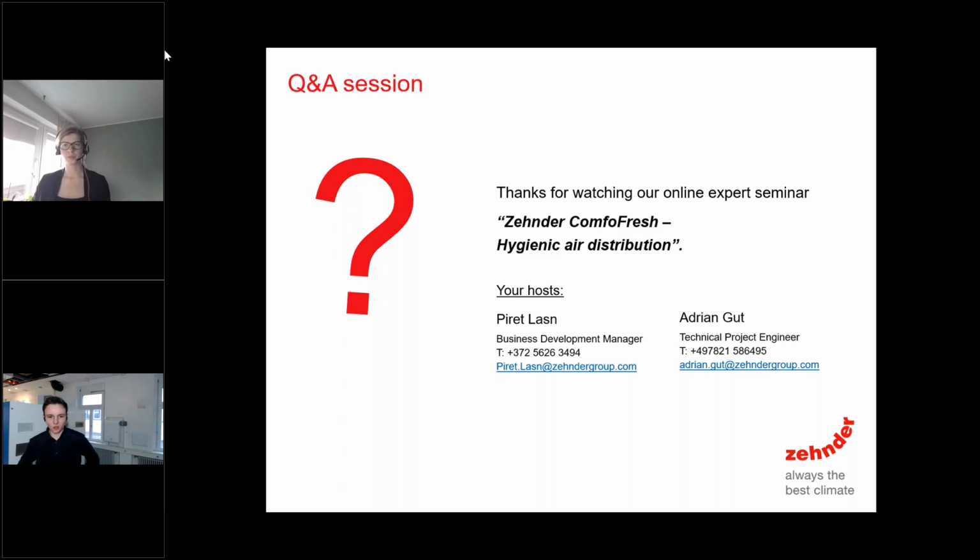How do you connect the ComfoAir 70 to the tube? Actually, the ComfoAir 70 is a decentralized unit, so usually you do not connect it to an air distribution system. But for the ComfoAir 70, we have the opportunity to connect a second boom, as we explained in the last webinar.